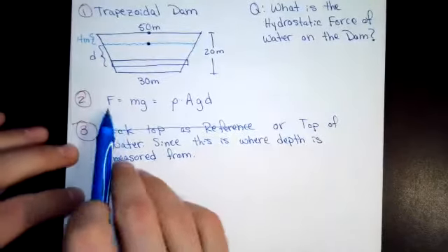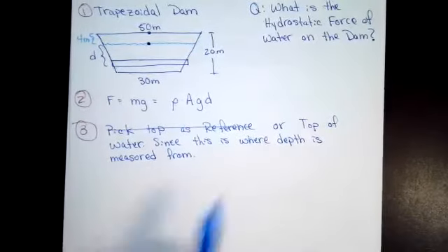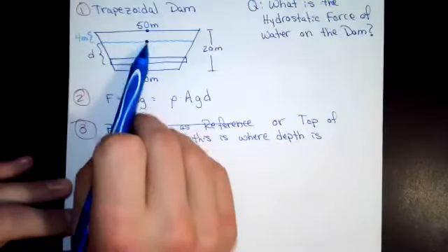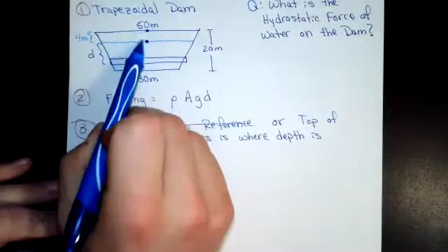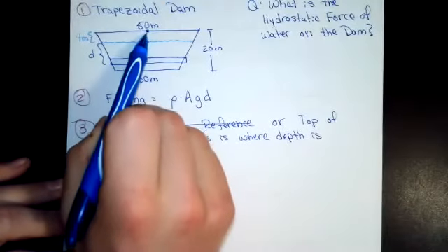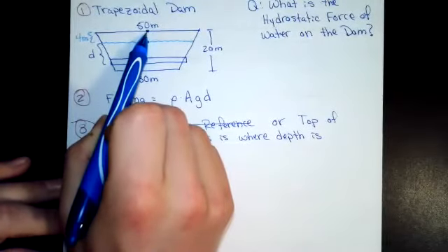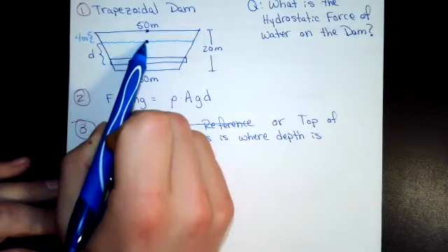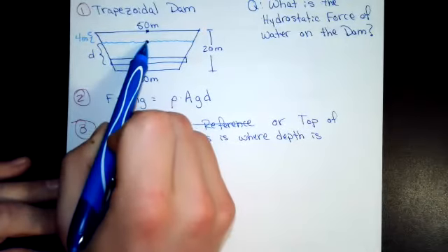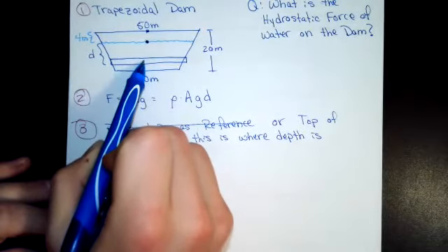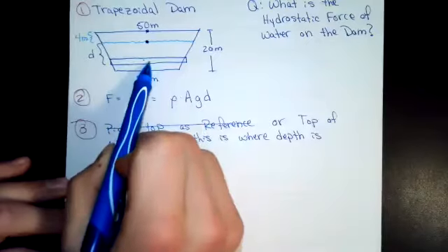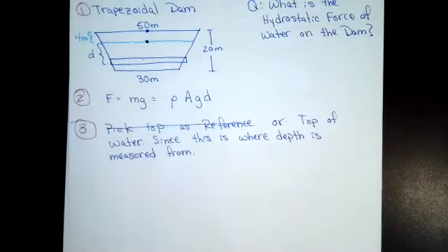And since the force depends on the depth, it'll be a natural choice, since then we won't have a linear shift. If I pick the top here, it wouldn't be bad. It's just that where does the depth of the water start? It would be 4 meters plus whatever depth we are below that. And we would just have to make sure we take that into account.